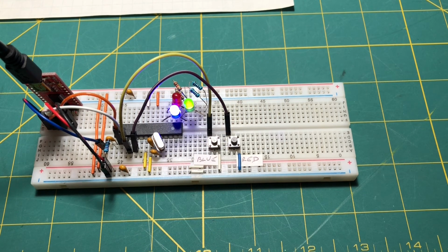Alright, so the main advantage of using the interrupt method here over the polling method is that the interrupt can take place at any time while the green LED is flashing, and it can be serviced at any time. Whereas when you're polling, you have to wait until the green LED has finished its flash sequence. So there will be issues with timing where you're hitting the button and causing the change of state, but it's not being detected in the polling method, where it's always going to be detected here in the interrupt method.